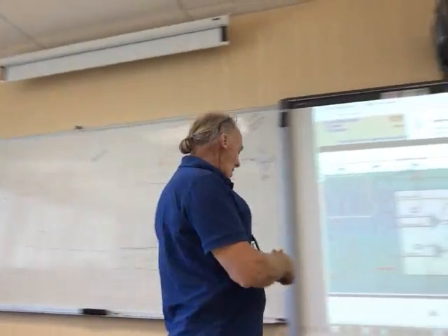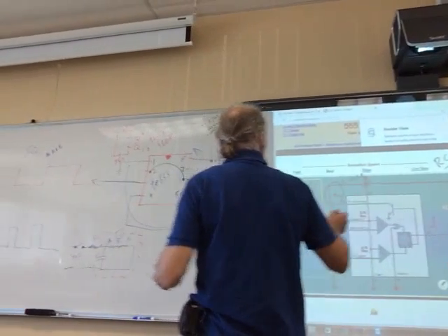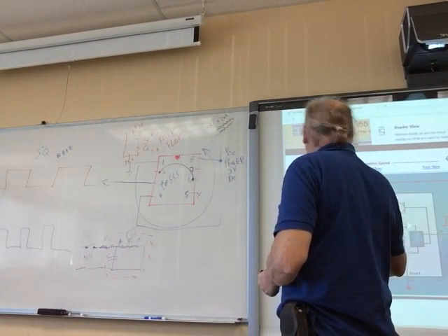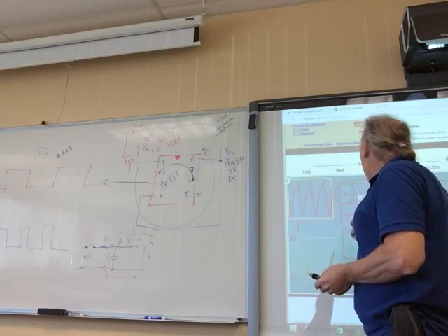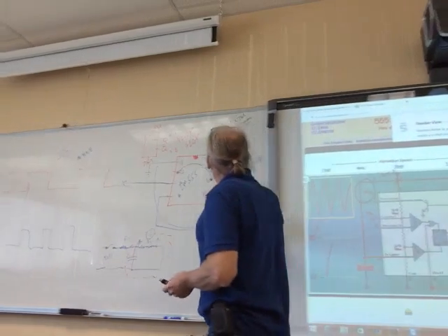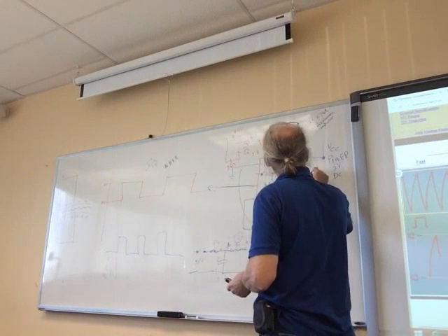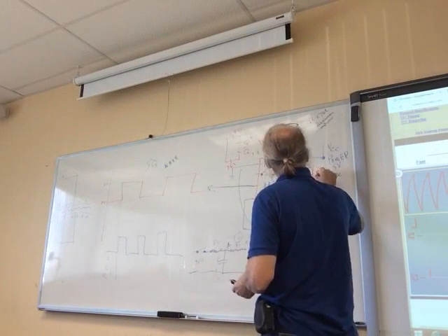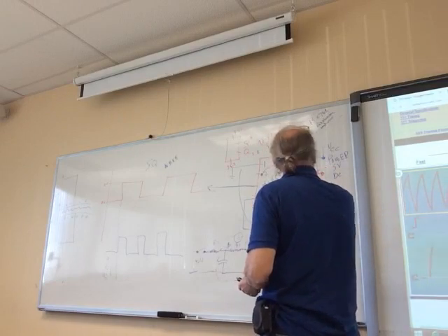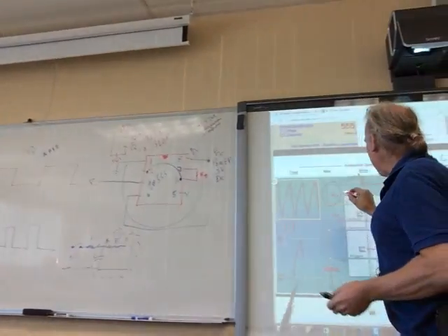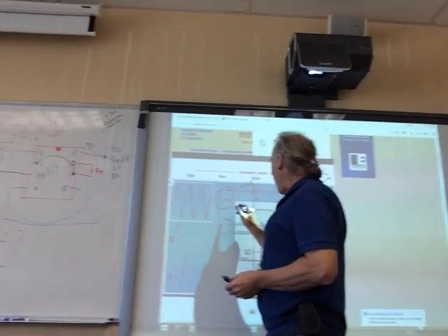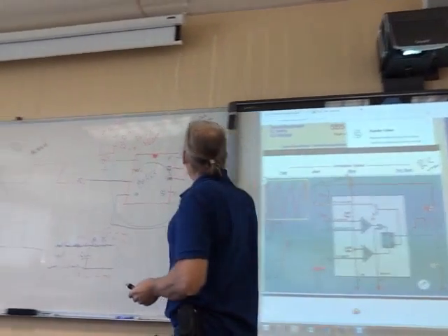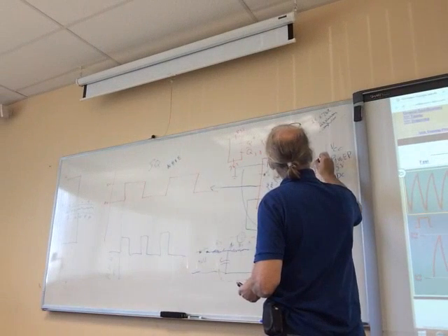All right. So now we know, but we have to know how to hook it up. Well, if we look at this, we go, oh, let's see. 2 and 6 are connected together. We've already got that. We need an RB between 6 and 7. So we're going to place a resistor between 6 and 7. We'll call it RB, just like they did. Oh, and we need a charge resistor, RA, to B+. And it comes off of which one? 7.